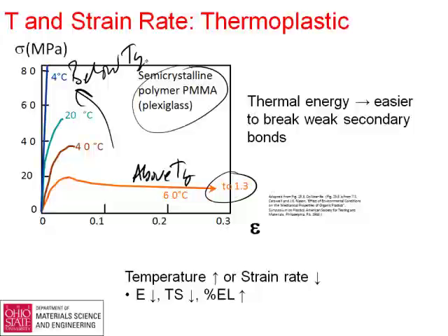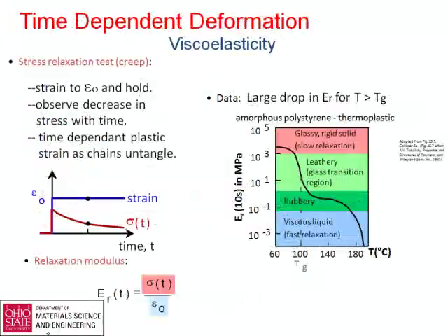And you see that that's causing the material to get much stiffer, much stronger. Elongation goes down dramatically. Again, if you take this material and you heat it up again, you can do the shrinky dink effect on it. Polymethyl methacrylate works nicely with that.